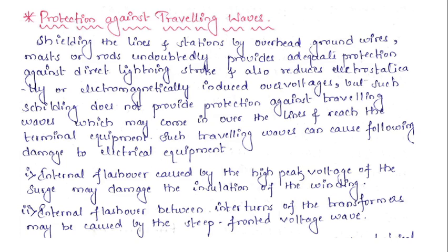First we need to understand the meaning of a traveling wave. A traveling wave is a temporary wave that creates a disturbance in the system and moves along the transmission line at a constant speed. It is because of the lightning phenomena. It is a temporary wave which is present in the transmission line. Such a wave occurs for a short duration, that is, in the order of microseconds, but causes much disturbance in the line.